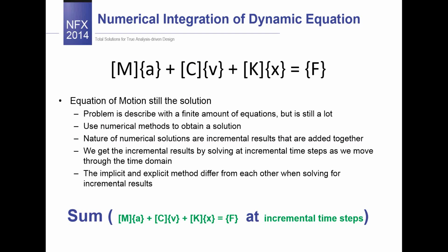And at this moment, it's very important to say a few words about the main dynamic equation and basic concept of its solution methodology, which refer to the numerical time integration. So the equation presented on the top is the one which is being solved during the analysis, and I'm sure that you remember this from high school or college. And this equation is created or assembled for every single degree of freedom in your model.